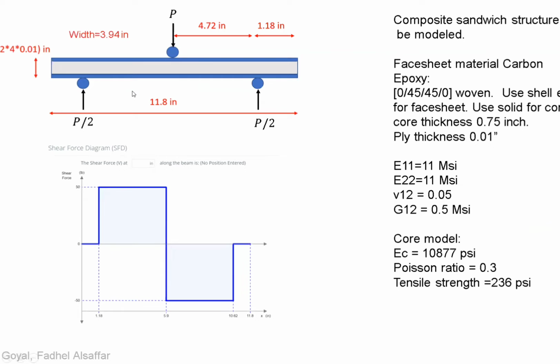these kinds of constructions. Composite sandwich structures really are made of a laminate on the top face sheet, a core in the middle, and a face sheet on the bottom. This sandwich structure construction improves bending performance, and is used in a lot of different applications, including surfboards and many other structures, such as launch vehicles.